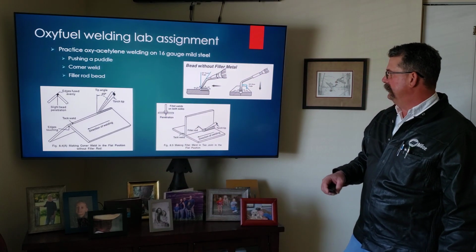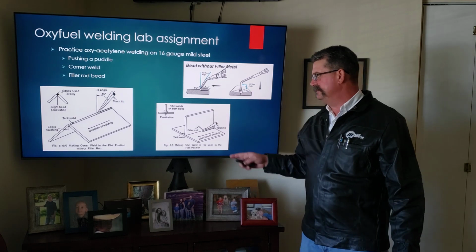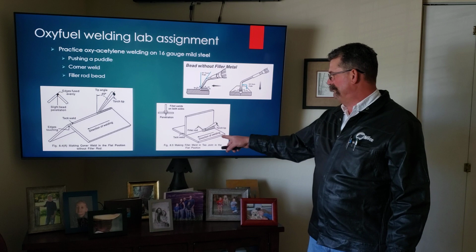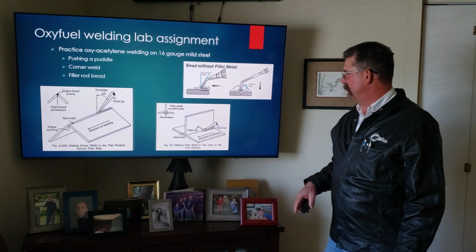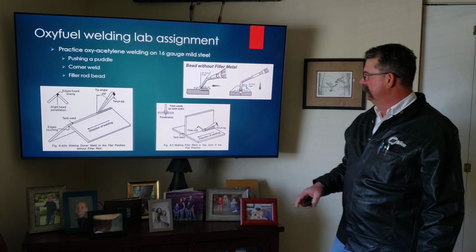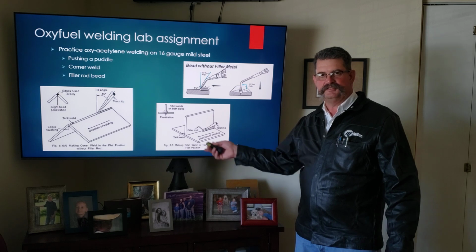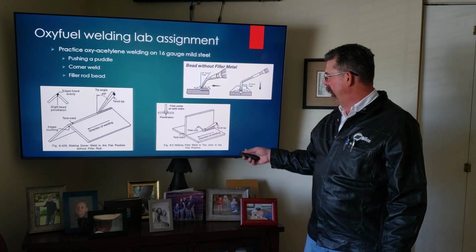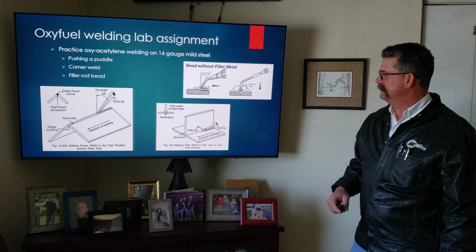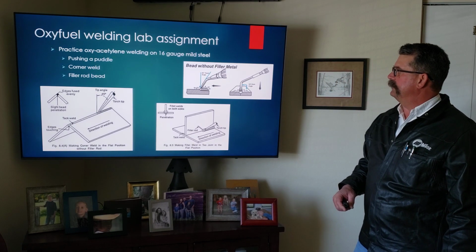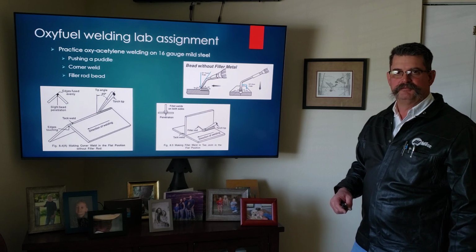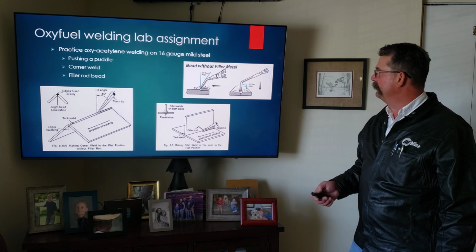As we increase in skill, increase in technique, have students move on to doing some type of a filler rod bead. Not necessarily a T-weld. This is a little more advanced than just running flat beads, but definitely a good exercise in developing practice with an oxy-fuel welding setup and learning the importance of fusion and heat within the weld.